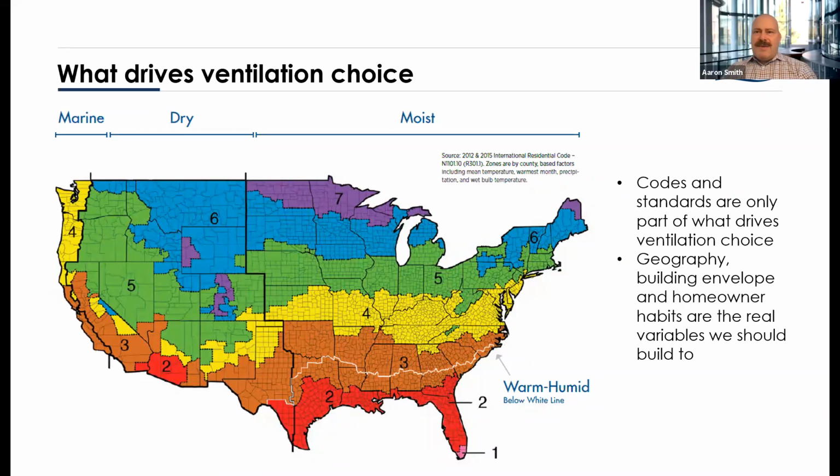And just a key point on that, you have to be careful. You can't always take your flat media filter out, drop a MERV 16 in, and hope for the best. You may create enough air pressure drop that the air conditioner or furnace then doesn't operate correctly. You might be better suited to getting an air purifier from April Air and putting that in line. That MERV 13 or 16 is going to be a pleated, deeper media that's going to allow proper airflow across that system. Is that right, Joseph?